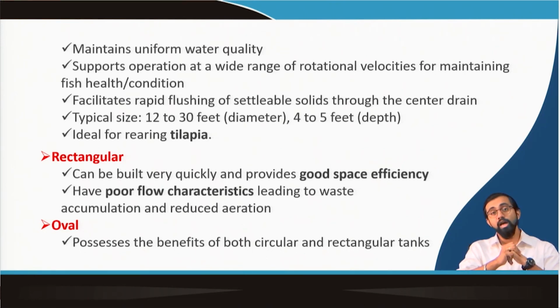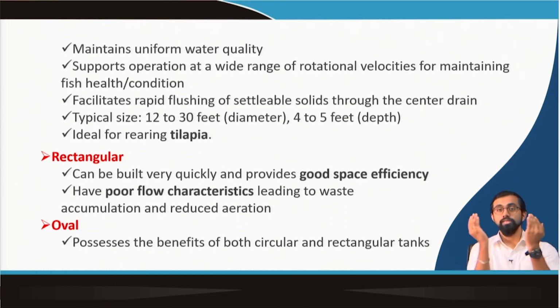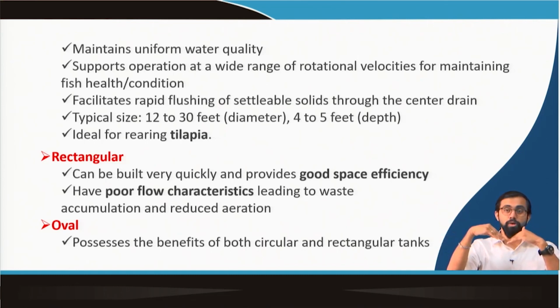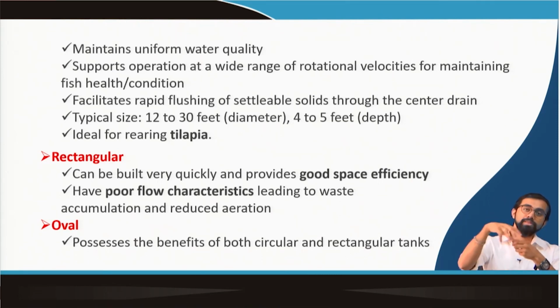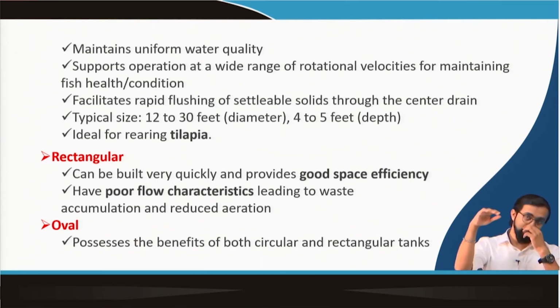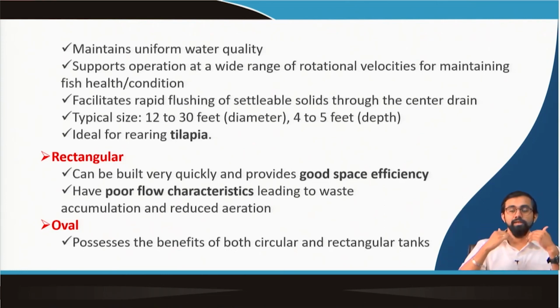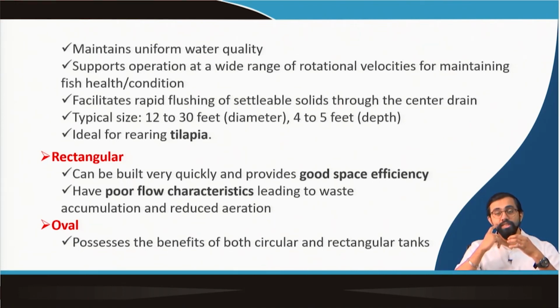It can facilitate rapid flushing of settleable solids through the center drain, because it's rectangular in circular nature, and it has a particular slope, which looks like a kind of hovering structure. So in the middle of it we have the center drain. Because of this slope, all the settleable solids will wash out through this center drain. It has a typical size of around 12 to 30 feet in diameter, and 4 to 5 feet in depth, ideal for rearing tilapia.